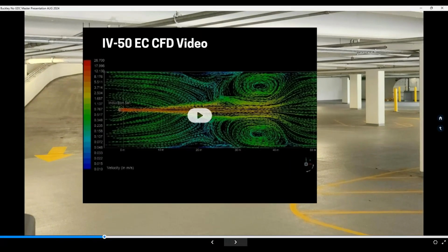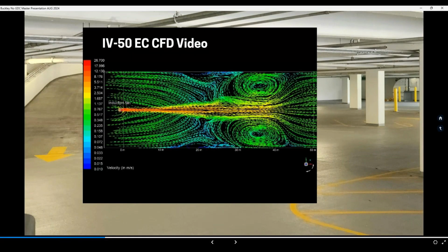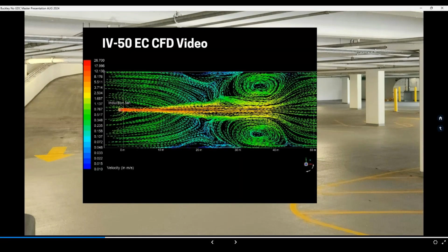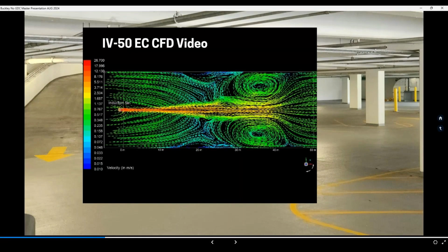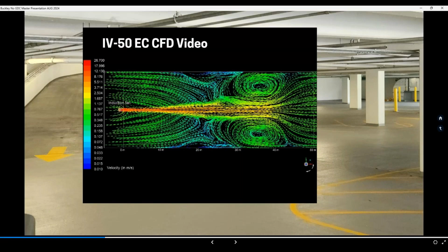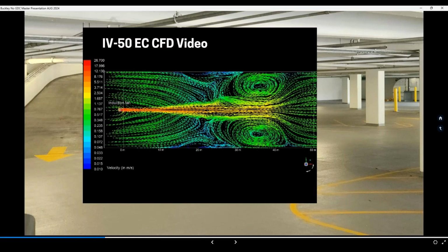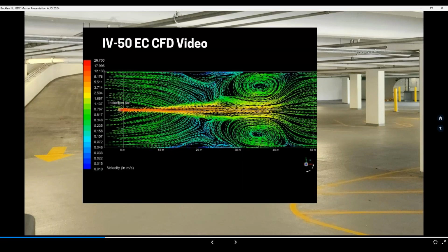So now we will look at a centrifugal jet fan in operation. Now you notice the difference here is a centrifugal jet fan. It is a little slower moving. It doesn't have the high airflow CFM, the same as a high thrust axial jet fan, but it puts into motion a considerably larger area of induced volume of air.